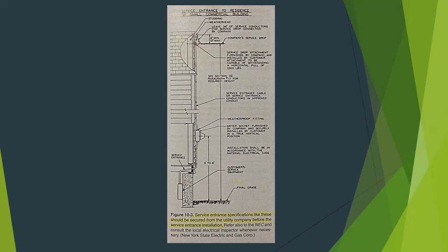The service panel should be located in a central and accessible area near the major electrical equipment of the building. The service equipment must be protected from physical damage, water, and dust. And the service equipment cannot be placed in bathrooms, storerooms, closets, or damp cellars.